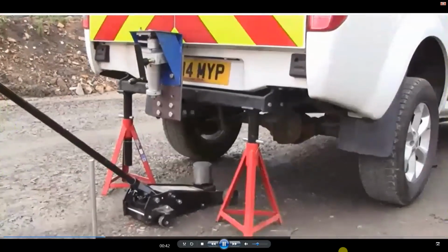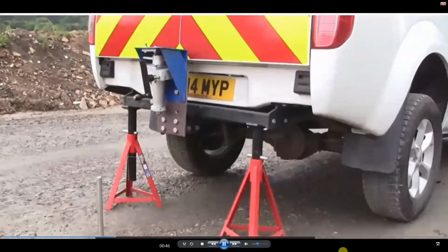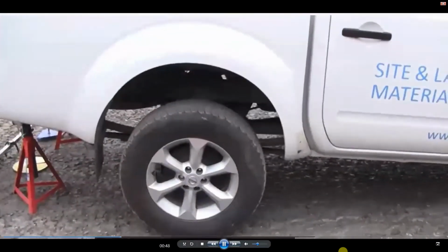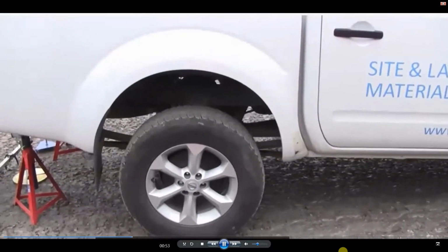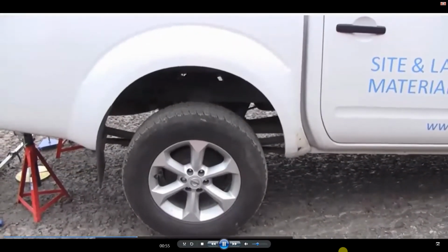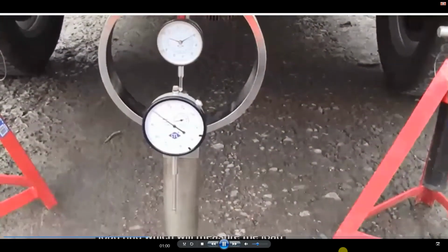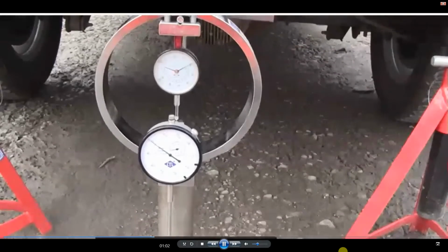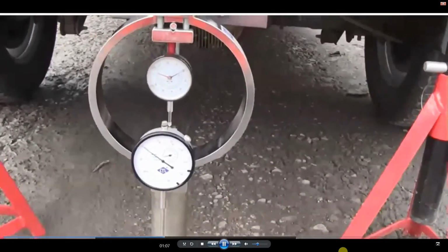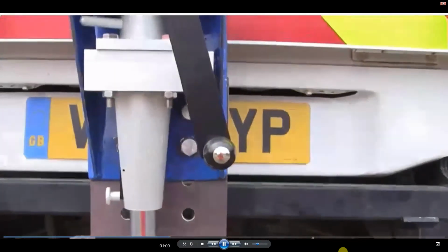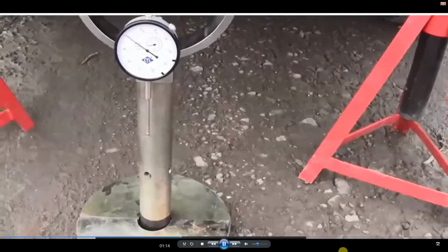With the jack down, we can then move that out of the way and continue with the assembly. And as you can see, the rear of the vehicle has been jacked up, so the rear wheels are just about clear of the ground. That we'll be applying, and there a larger gauge is a penetration gauge which will measure how far the plunger is penetrating into the ground as we wind that handle there. And on the bottom we have two surcharge discs as well.